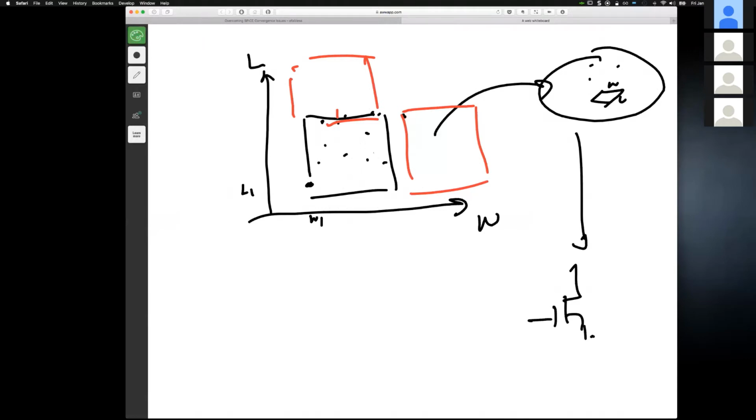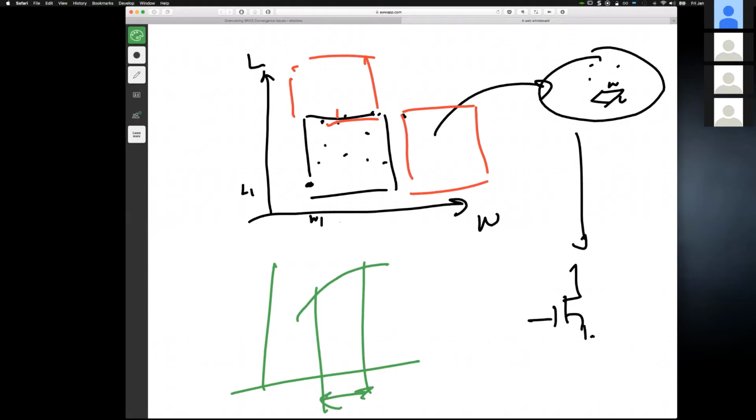If you're trying to fit a certain effect in a certain range of bias and W, you may use a part of the model, but if you want to fit it in a different area, you have to violate this one. So what happens is you start calibrating the models in the binning approach.